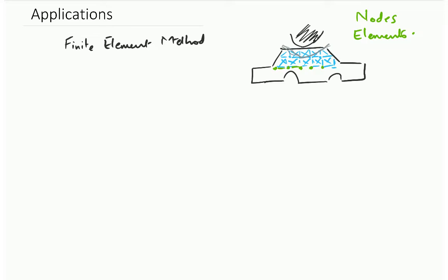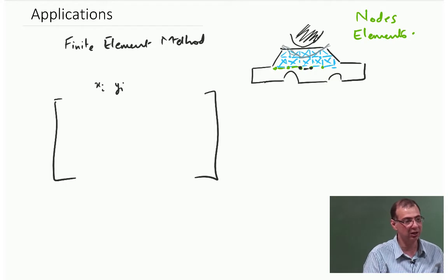What happens is that you have lots of variables. For each node over here, you're going to have some variables which may correspond to the location, the acceleration, velocity. So there will be a lot of variables associated with each node. And then these elements between the nodes are going to represent the stress and strain relationships that are interacting between the nodes.